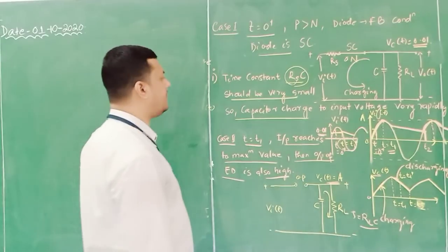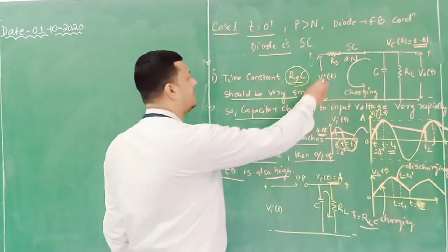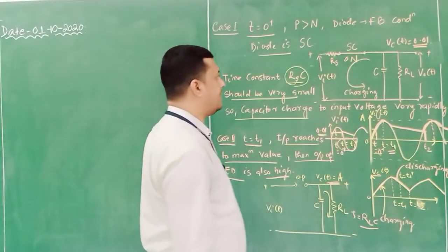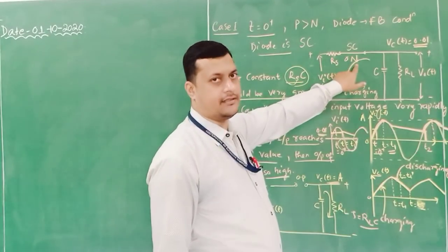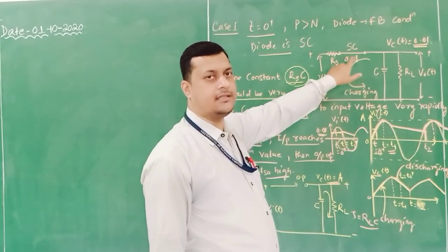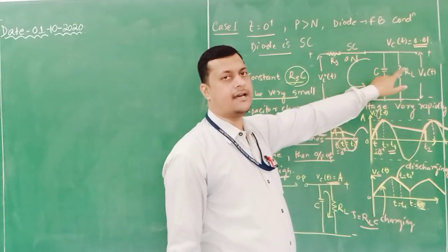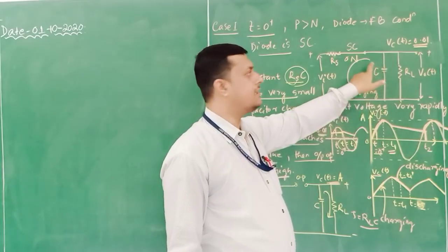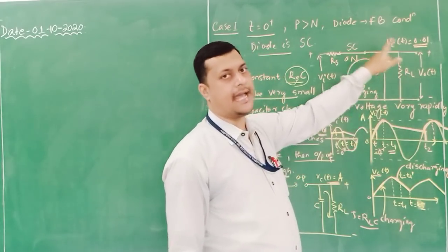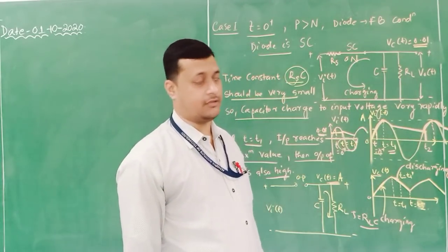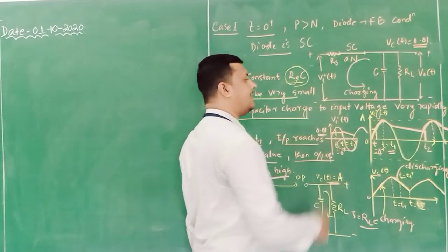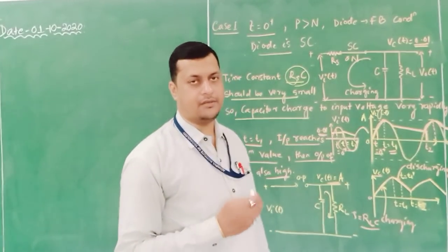So first, here you can see that the input is provided to our envelope detector. In the envelope detector, the diode is followed by R_L with respect to C. R_L means load resistance, and C. So this particular filter also acts as a smoothing filter. Okay, so now how does it work? It is simple to design.